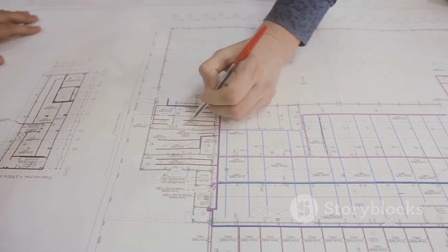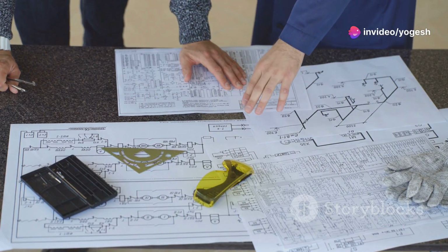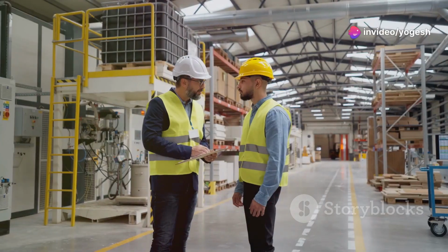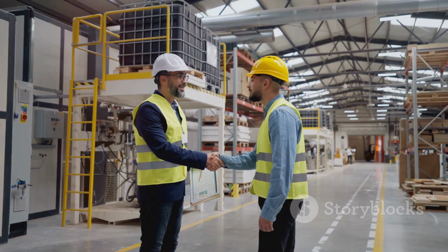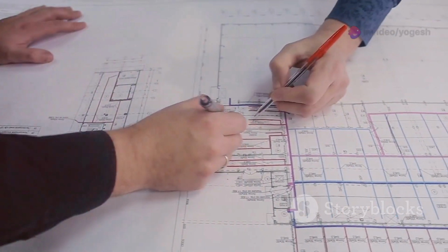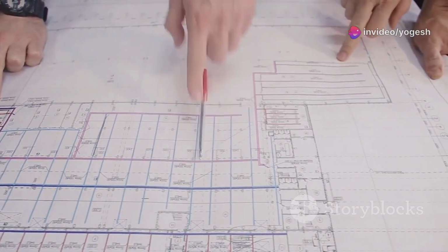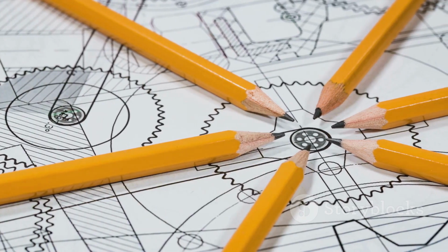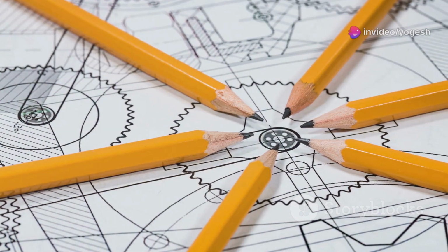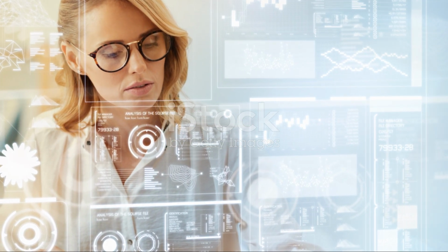Before sending a drawing out, always ask yourself, can a machinist build this part using only these numbers? If the answer is no, go back and fix it. Developing this habit will save you time, money, and countless headaches down the road. It's a small step that makes a big difference. Remember, clear, complete, and non-redundant dimensions are your best friend. Never assume anything. Clarity is everything in engineering. One missing or extra number can ruin an entire project, leading to delays, rework, and frustration for everyone involved. So, always double-check every drawing before release. A careful review now can prevent major problems later.